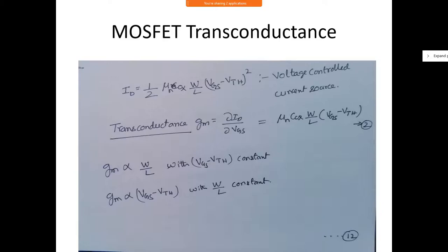So what is called conductance? What by what is conductance? I by V is conductance. Okay, why is it called transconductance? That is important. We discussed it already. Trans: output current and input voltage. So we are referring to two parameters which are at different ends. ID is output, VGS is input. So we are referring to two parameters at output and input. That's why we refer to it as transconductance.